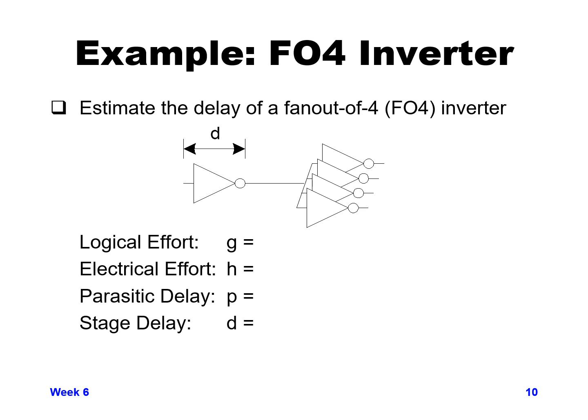So first, let's go through the various different logical efforts. An inverter has logical effort of 1 by definition, so G equals 1. Electrical effort, in this case our C out is 4 inverters and C in is 1 inverter, so our electrical effort is H equals 4.